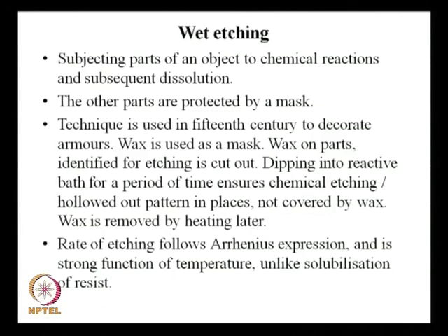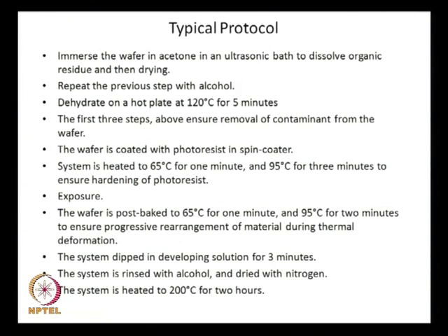Now, the rate of etching follows an Arrhenius expression. You must understand one fact here: you have earlier dipped the substrate into a developing solution. If we go back to our previous discussion, in the typical protocol that we discussed, near the end you can see we have mentioned that the system is dipped in developing solution for 3 minutes. This developing solution is primarily to dissolve the photoresist material. This is just a solubilization process. So, this does not involve Arrhenius type dependence on temperature.